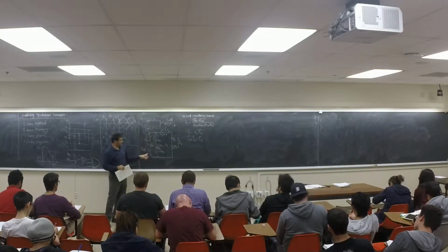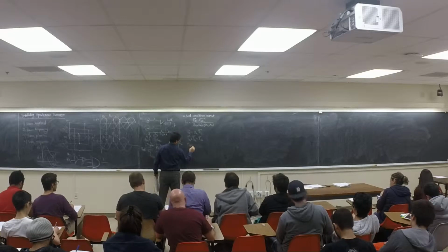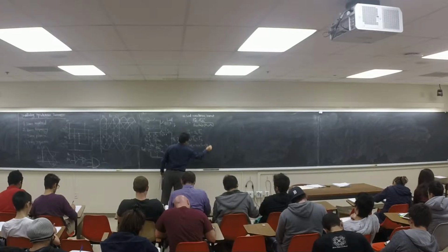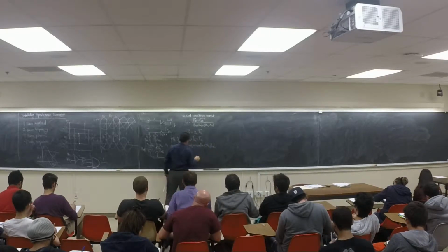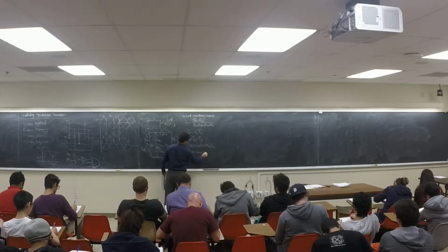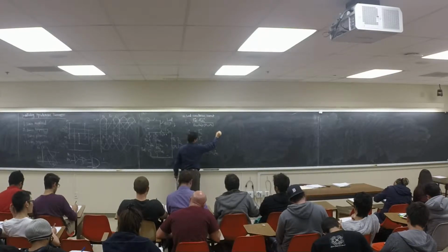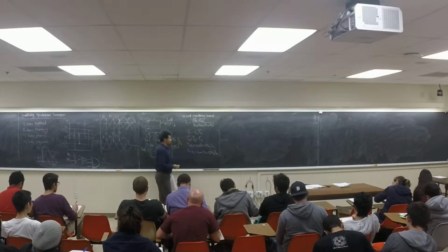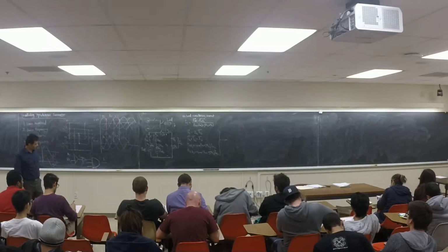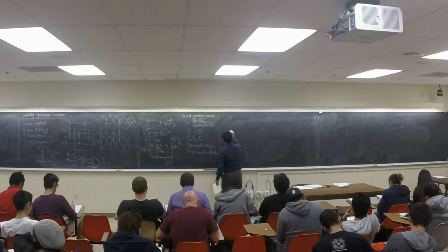Now, KVL here, we said it's the generator. EAF1 is equal to VT plus RA1 plus JXS1 times IA1. And the second one is EAF2 is VT plus RA2 plus JXS2 times IA2. Right? We have these 4 equations to solve it. If you solve this equation,